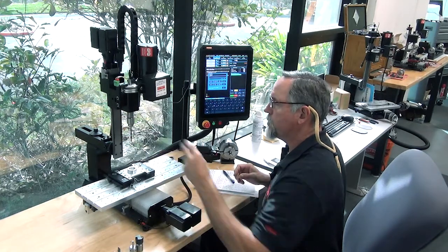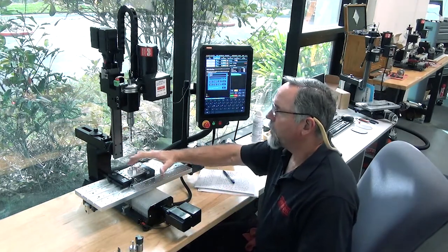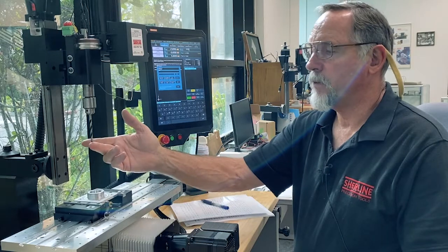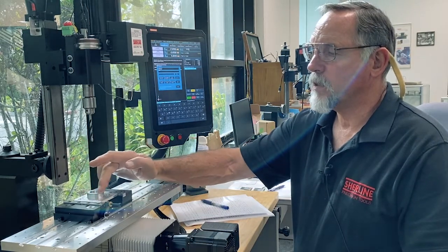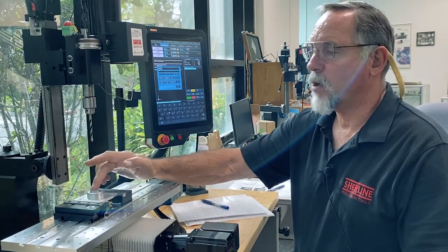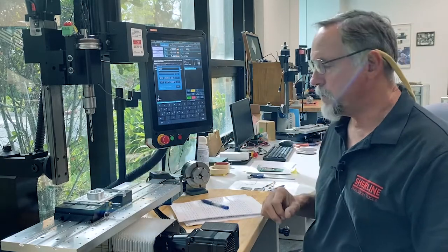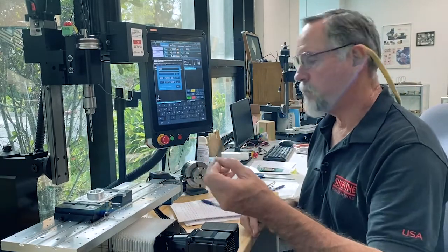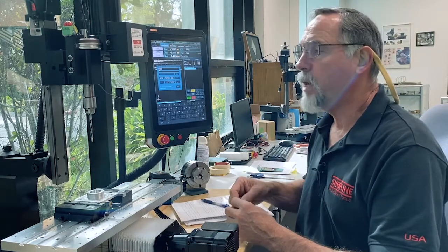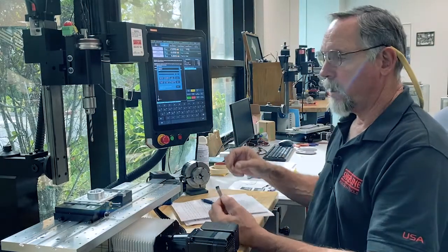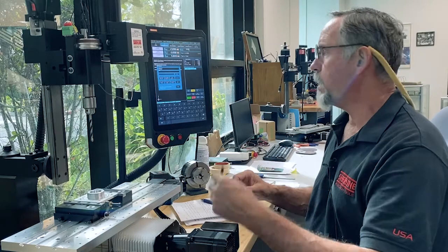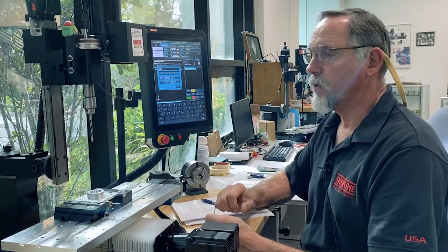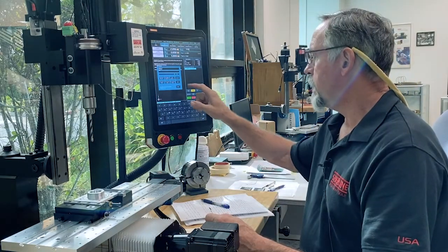For general tool setup, for my tool offset, I'm going to touch the tip of the tool to the top of my part. The top of my part is always going to be 0 in my programs. I've got a piece of 1 thou shim stock. You can use a piece of paper, whatever you want, as long as within a thou or a couple thou, all your tool offsets are going to be close enough to work with. I'm going to hit exit.